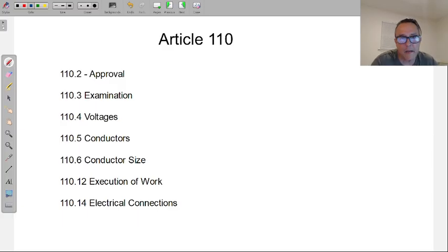All right, and when we get to Table 310.16, we'll get to it in a little bit, if we can get to 110.14, which just looking at the time, it's 6:13 maybe. This table is going to separate in half copper and aluminum clad. So if I don't know what we're connecting to this, like I don't know if the building people that we're bringing this piece of equipment to are going to want aluminum wires, they can ask for aluminum wires, or for whatever case aluminum is going to be used, but I don't know that.